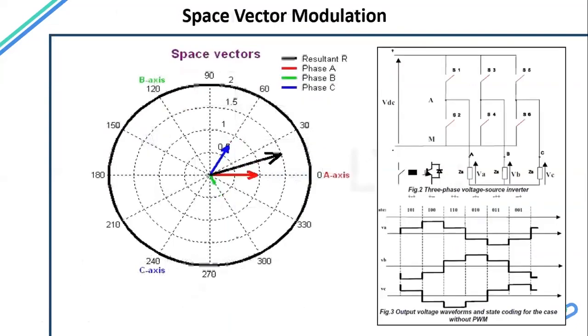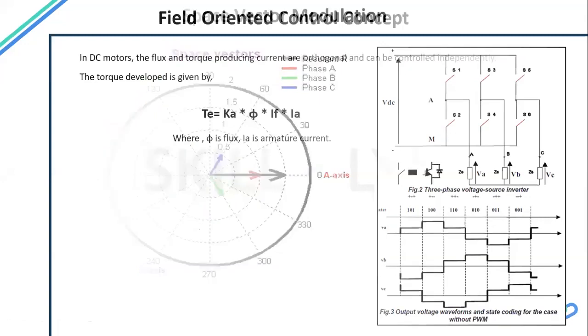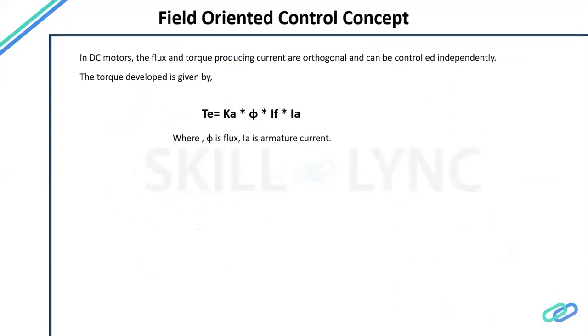So you can see this is where, instead of switching to the 6-step, rotating. So this is a space vector modulation that we typically implement in our FOC, field oriented control. This control strategy is also impacted in the design of the machine, what kind of control strategy that we will have. So let's go to the control now.